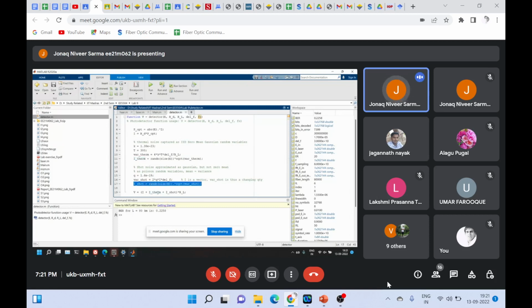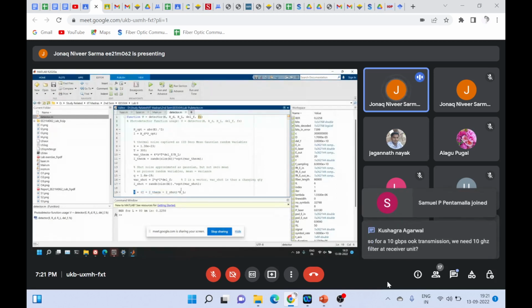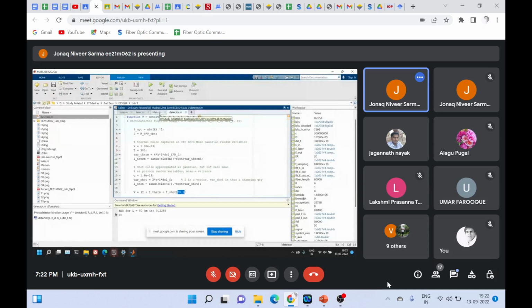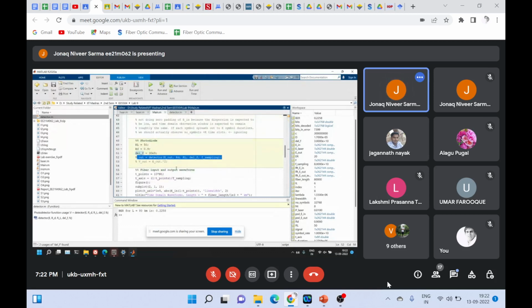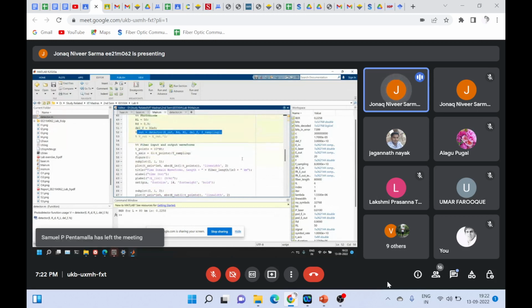The total current you will get is the current you should have gotten because of the optical power input, plus this thermal noise term and the shot noise term. And the rest of the code takes this, so we are multiplying by the load resistance. Clear?